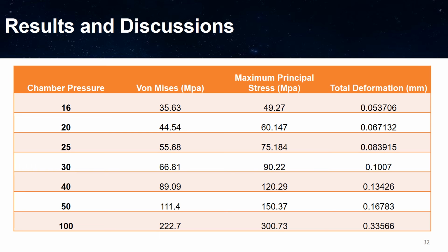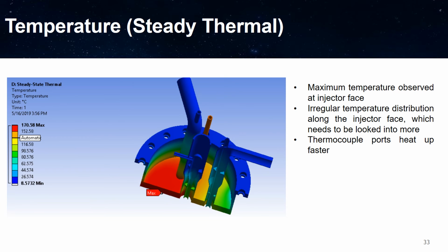So the yielding stress of 90 megapascal of Inconel is basically fine for this design, and we can go on with the same design and test up to 100 bar for structural conditions. Now let's look into the temperatures.